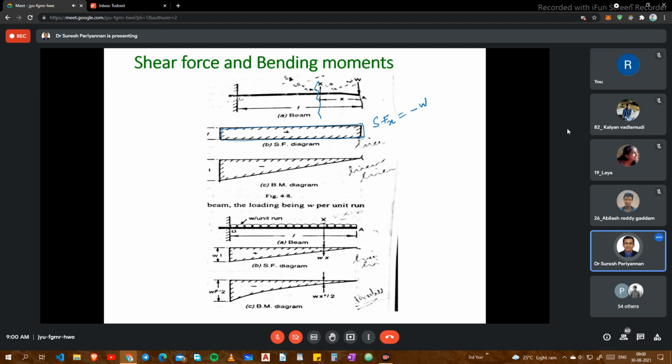There's a diagram, because this is very important when we are going to discuss the further topics, the components of design. This is also very important when you are going to discuss next semester's DTE, design of transmission elements. Even last semester I was teaching this subject. I'm going to teach the same subject DTE in the upcoming semester, maybe. Okay. Now the bending moment with respect to x here, bending moment Mx is equal to minus Wx. Now the bending moment is linear behavior.